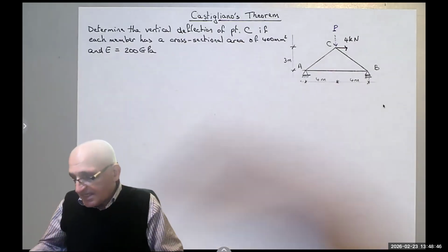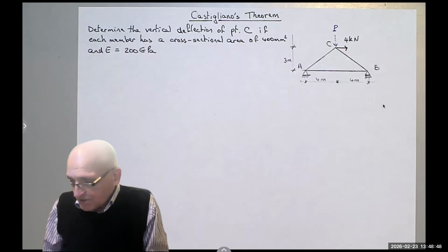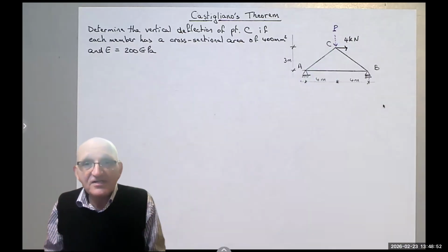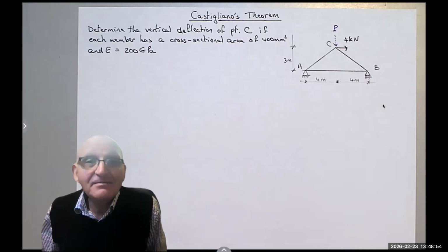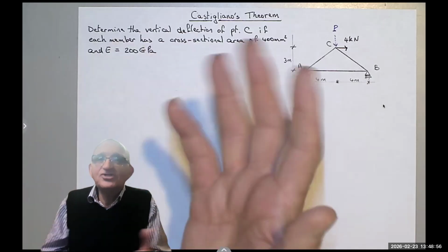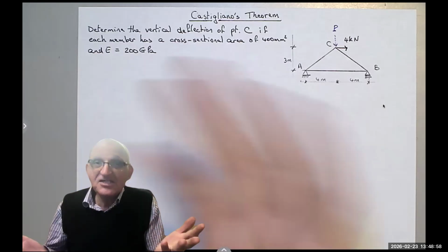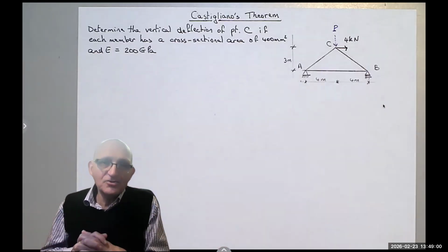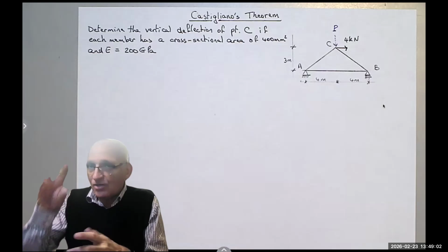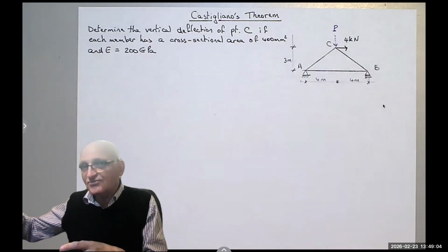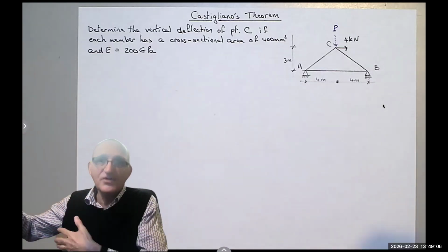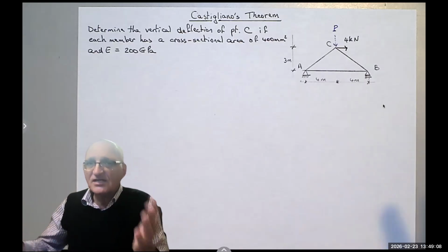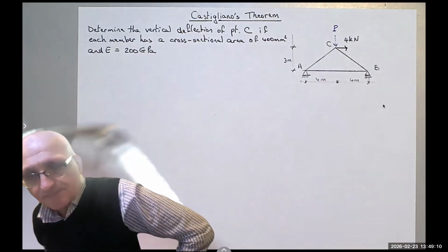And then we can say, alrighty, I'm going to take the derivative of all the forces with respect to P. And because P didn't exist, you just used it, right? It's fictitious. You have to set it equal to 0. So we only use it to find the derivative of the forces with respect to P. But once we are done with that, set it equal to 0.